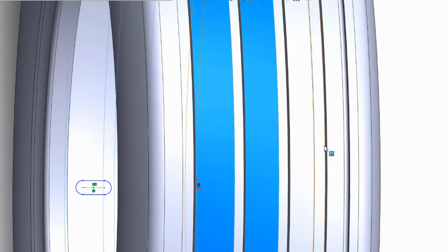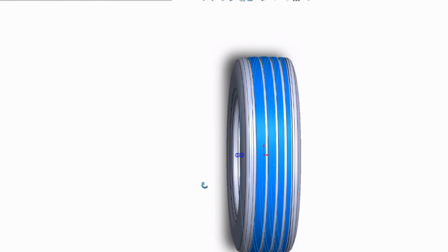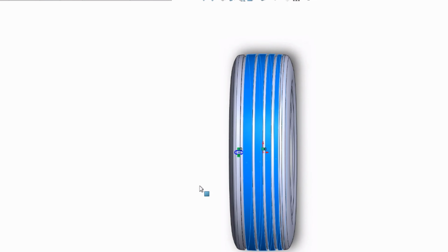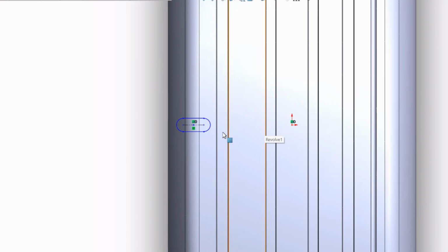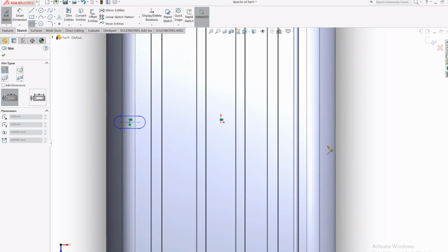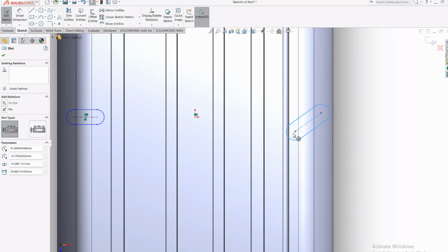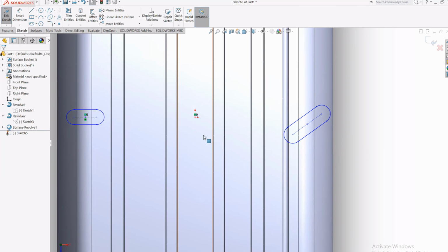One thing to note here is that we need to make cutouts over these ribs. Therefore, the sketches will be made in such a way that the material removal is possible. So now, make sketches for shoulder cutouts first. The outer side we are making straight circular slots for large contact area and carrying extra load. And on the inner side of the tire we are making angled circular slots for quiet ride and better tire bite.